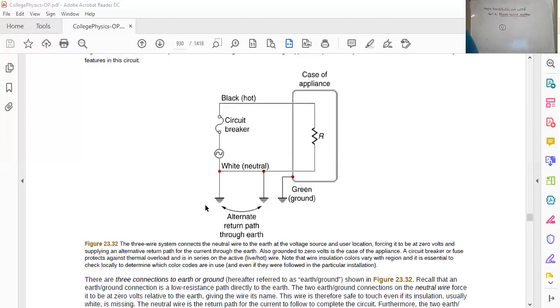You want to ground to 0 volts. You want to make sure that you, as the person walking around the house, are walking around at 0 volts, and that your device and the wiring, the neutral wire in the system, should be grounded. Actually the case itself should be grounded. The case itself may develop a different potential, so you want to ground the case. If you don't ground the case, you can have a shock. So there's a possibility of a shock in that case. Again, you want to try to maximize all the various earth ground connections.